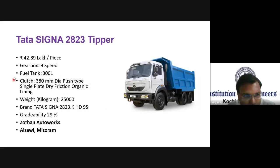Each vehicle costs 42.89 lakhs, and is going to have a 9-speed gearbox, and the fuel tank is with the capacity of 300 liters. The clutch is 380 mm diameter, and is going to be a push type. It's a single plate dry friction, with organic lining friction material.